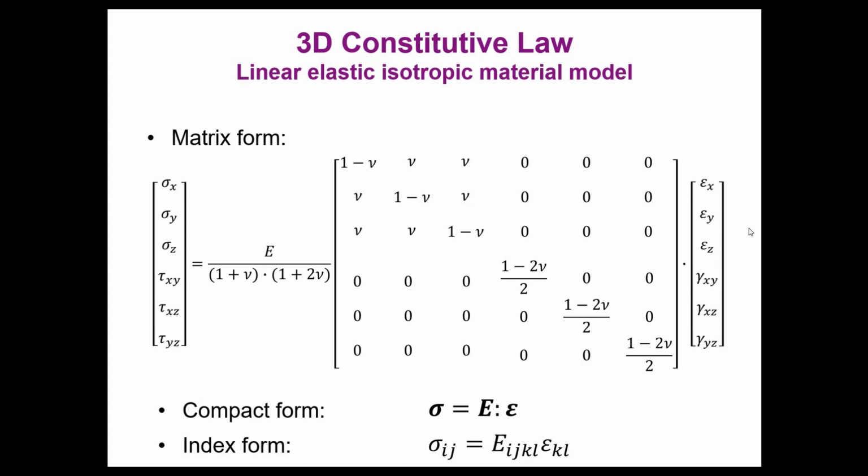So with all the components, the axial strains and the shear strains, or distortions, as they are called as well. So in a three-dimensional case, we can generalize the concept of the Hooke law by writing this tensor equation, where sigma is the stress tensor, E is the stiffness tensor, multiplied by the strain tensor, which gives you this relationship between stresses and strains.